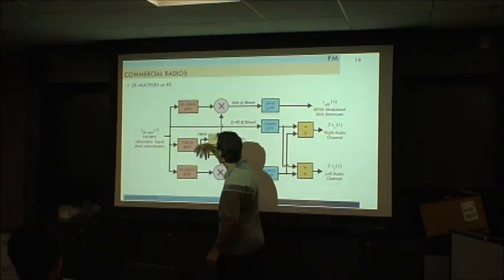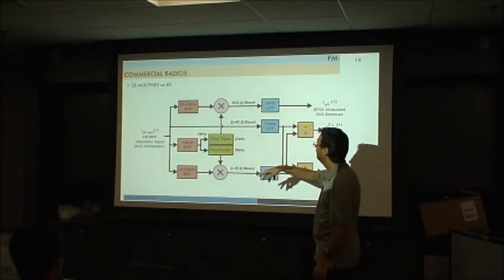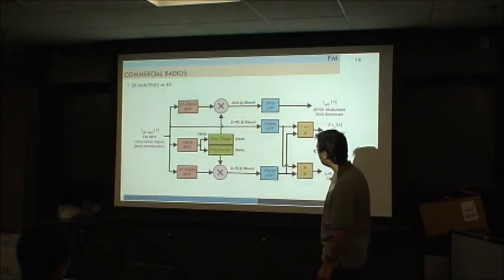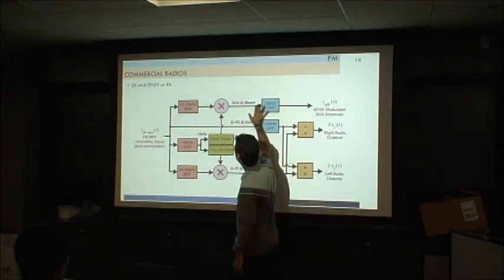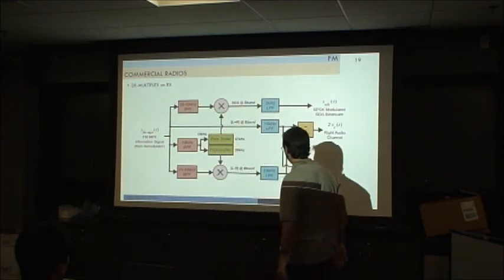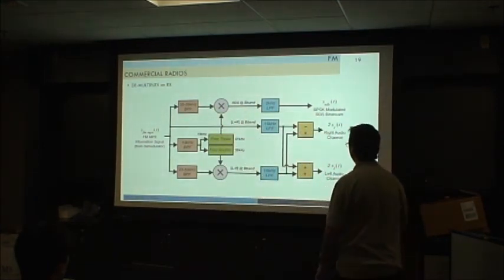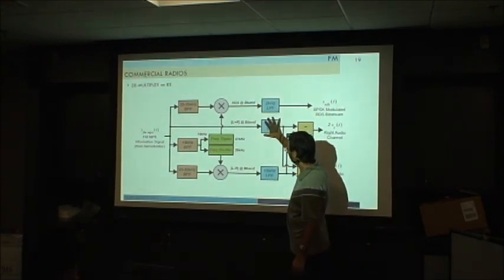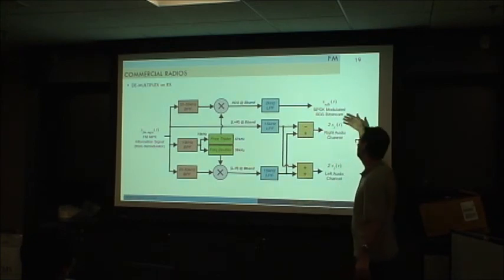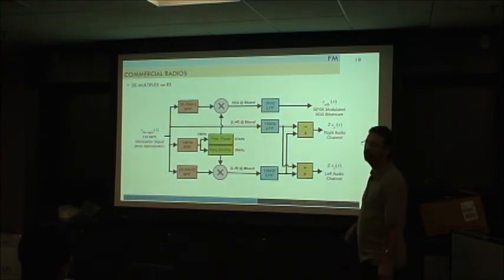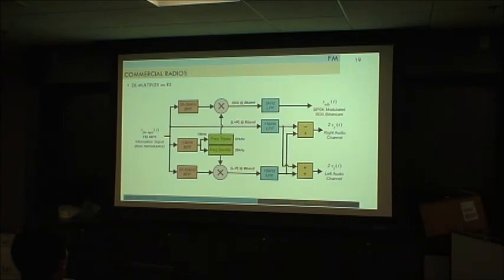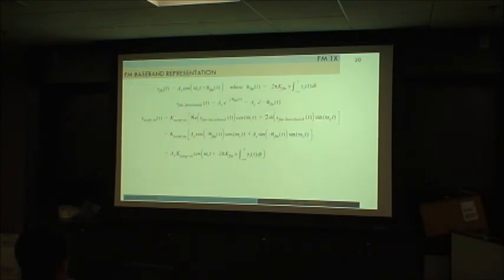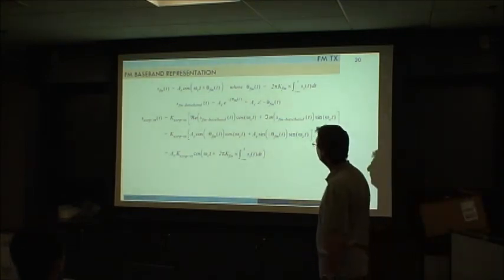And basically, of course, the 2 bandpass filters for the left and right, and you recover the signal. So we will not use this part. We'll just recover the mono here and left minus right here. If you combine it this way, you get double the right and double the left. So this will be on the transmitter side.